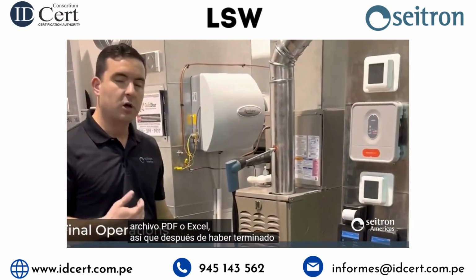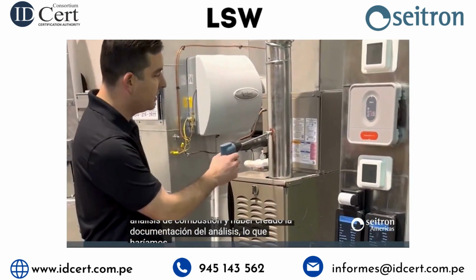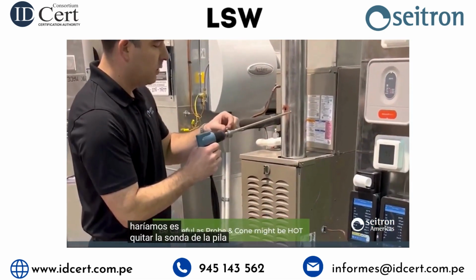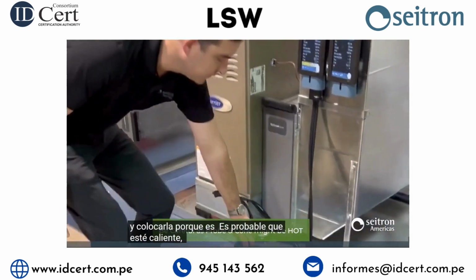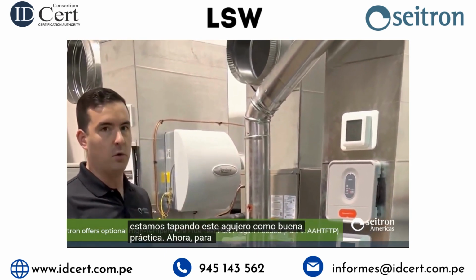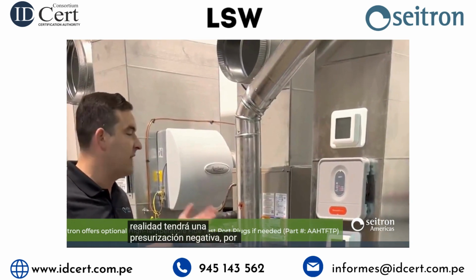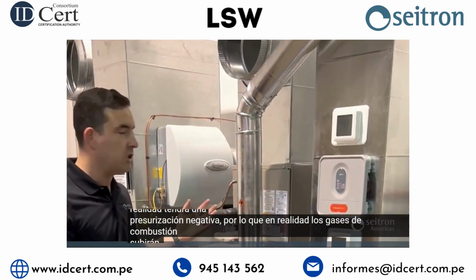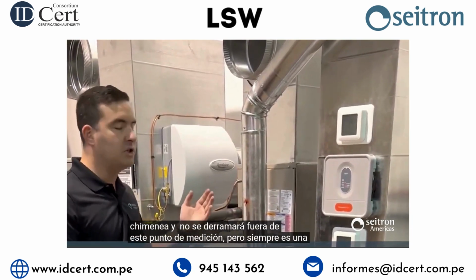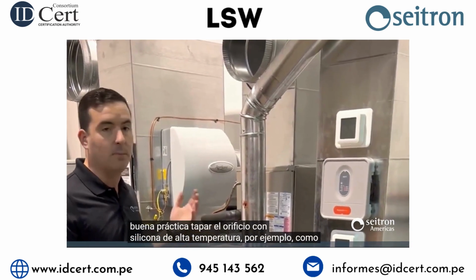So after we have finished our combustion analysis and we have created documentation of the analysis, what we would do is remove the probe from the stack and set this down because it's likely to be hot. We also want to make sure that we are plugging up this hole for good practice. Now for an 80% plus system, this is actually going to be negatively pressurized. So in reality, the flue gas is going to be going up the stack and will not be spilling out of this measuring point. But it's always good practice to plug up the hole with high temperature silicone, for example.